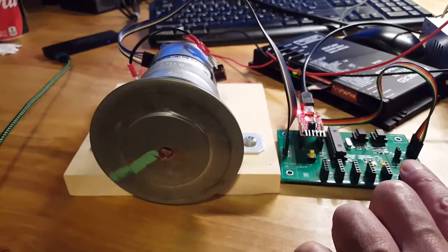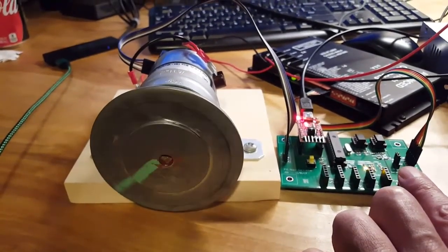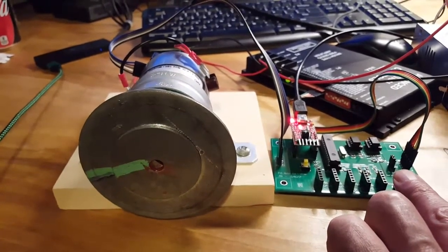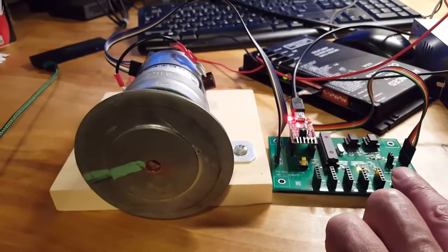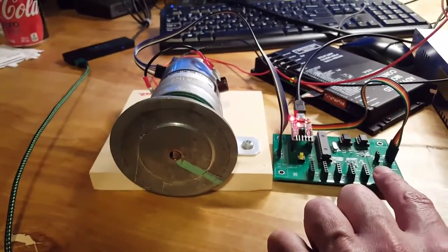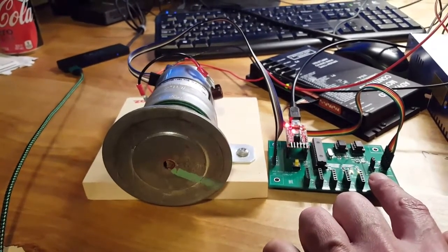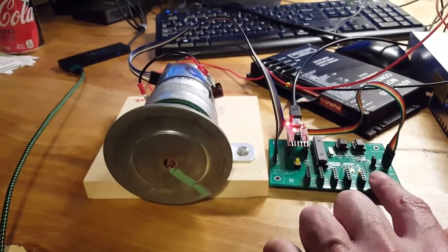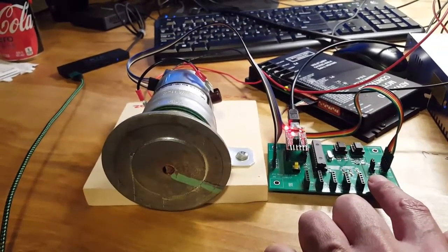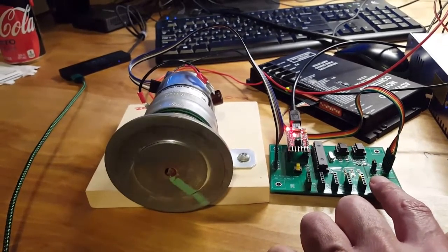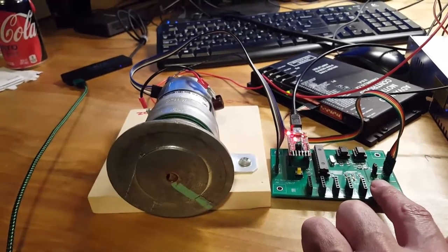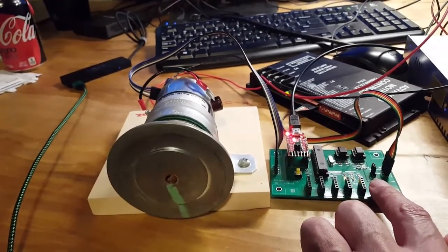Crank up the gain to put you at 45 degrees, damping ratio 0.7, and I still have too much static friction. It's not going between 0 and 5 radians. 5 radians is almost 1 rotation. Now crank up the gain to give you 20% overshoot, and I finally have enough voltage, enough gain to get the motor to spin. And there you can see the overshoot. Occasionally it spins and comes back. That's an example of overshoot for a position controller for a motor.